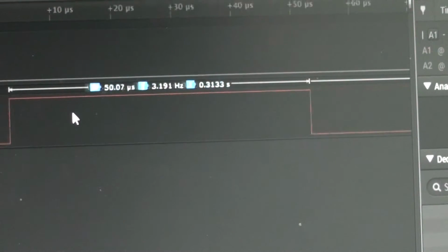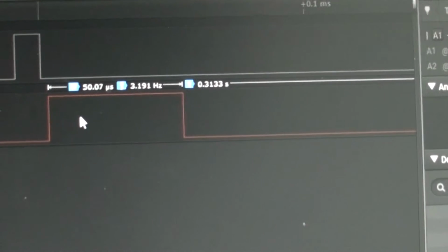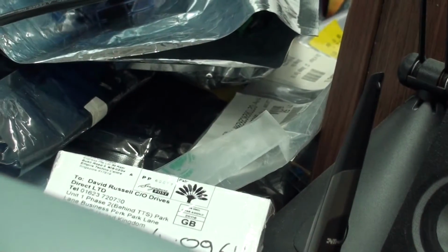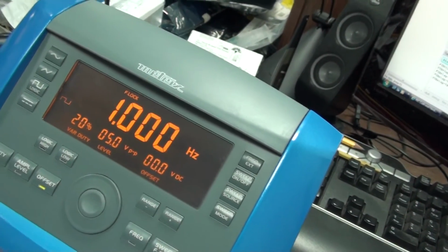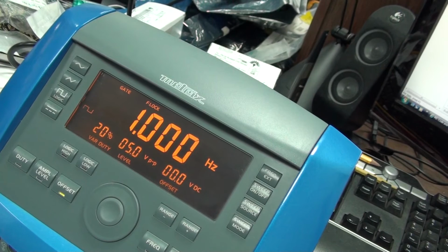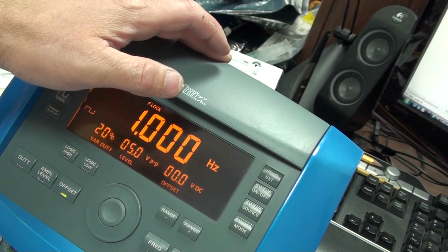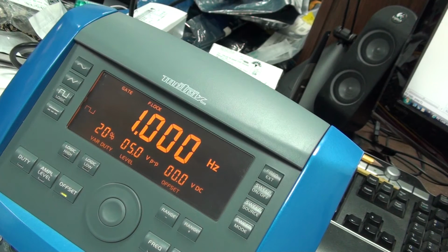So this is effectively working synchronously at the moment, because what I'm doing is in the main program loop I'm actually generating a pulse on a pin that's then coming through into P0. So now what I'm going to do is, rather than running synchronously from the program, I have here a frequency generator. So I'm going to hook up this frequency generator to provide the pulses, and then just changing the hardware at the other end, so that now rather than using the pin out on the microcontroller, we're actually using the pulse from the generator, and currently this is set to give a 1 Hz signal.